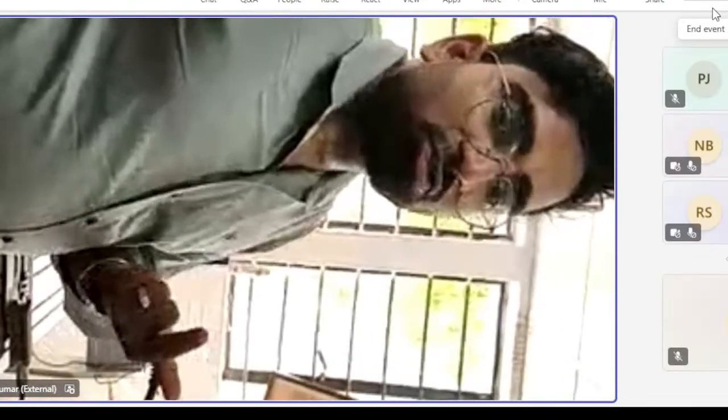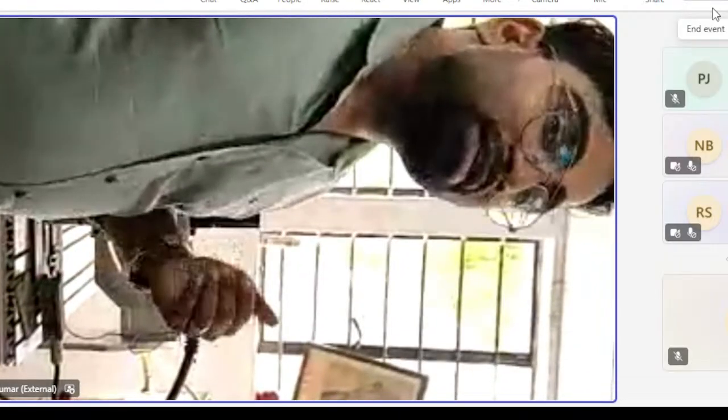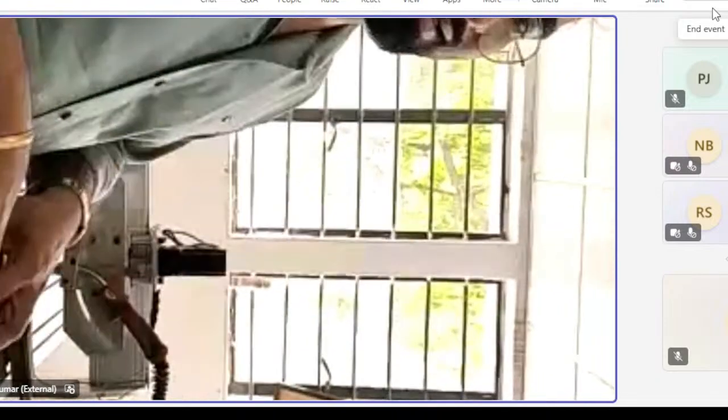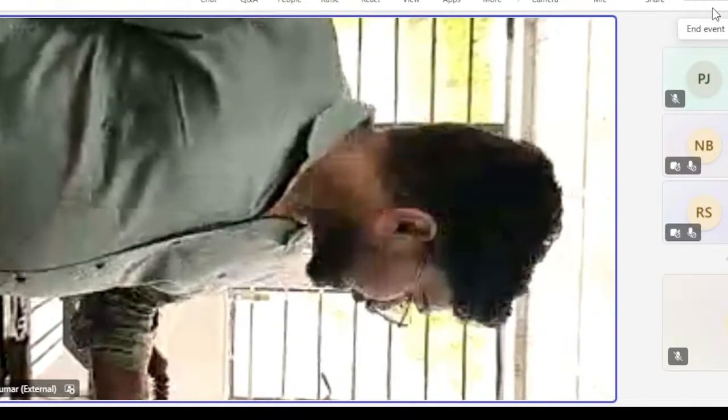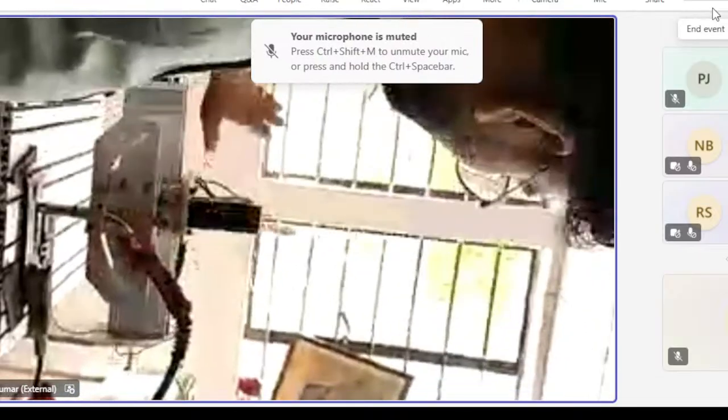Here in this case, if I define which kind of polarity is given, because we want higher deposition to take place, for that the electrode wire is given the positive part and the workpiece is given the negative part, so that the maximum amount of energy, about 2/3 of the energy generated in the zone, goes to the electrode part and the melting of the wire takes place. So I think you got the point why we took this part as positive and this part as the grounded part.